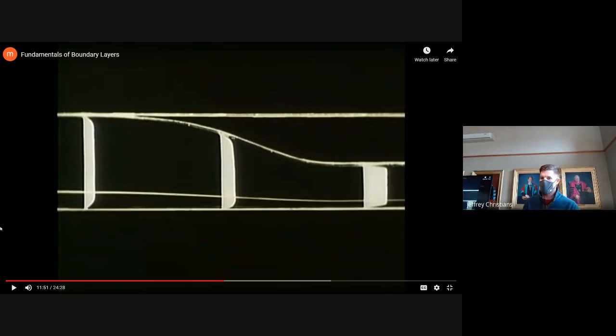Okay, so this is a contraction. So what do we know about the pressure? Well, as velocity goes up, pressure has to go down. So it's going to be high pressure on the left side, and then pressure is going to go down, and it's going to be low pressure on the right side. So pressure is pushing from left to right, right? So it's pushing the same direction that everything is moving. Pressure is pushing it, and velocities are going up.